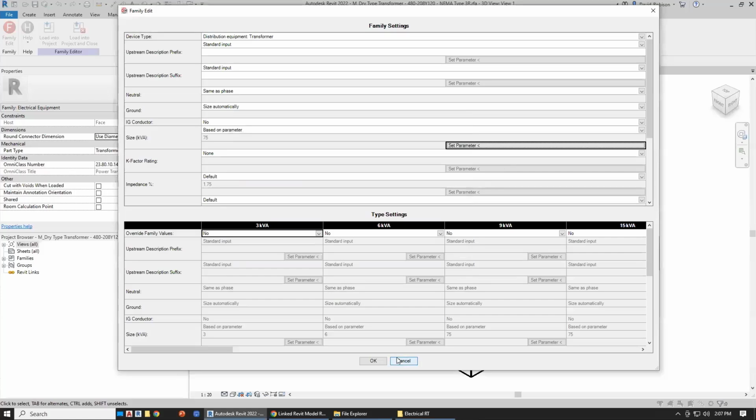And then once you've done that, load this family back into your project. Then when you put it in, Design Master actually knows what that kVA is going to be. Otherwise, it's going to put it in by default to 75 because we have to choose something. And that's something that we choose kind of in the middle there. So that's why they're all coming in at 75 because they haven't been defined otherwise. So define them properly, and then Design Master will know what to do with them.